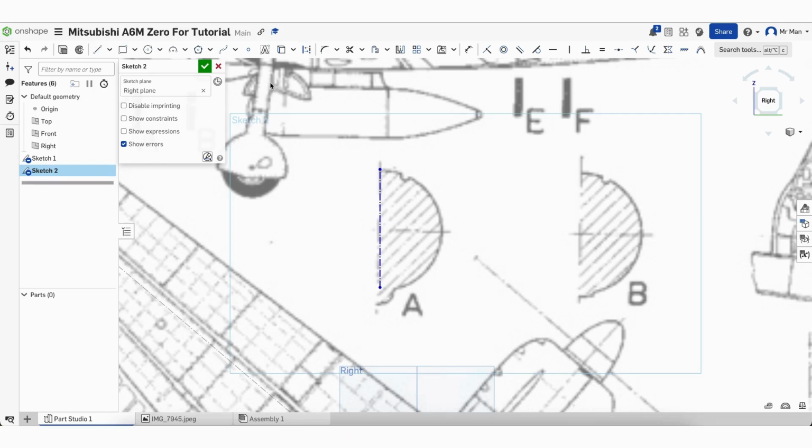Alright, now I would normally just grab the spline and drag it around like so. But since we're looking at basically a circle here, I'm not going to do that. I'm going to select 3-point arc, which is in the top left right there. Select those. Alrighty. Now make sure it does not snap to a full circle, because otherwise the skins will not work properly.